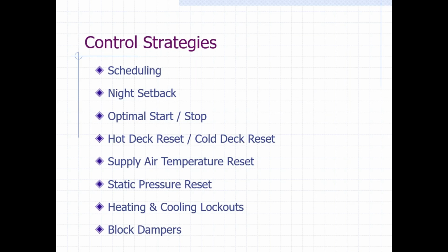climates. If you turn things off, then you might have some humidity issues in the building. And the last thing you want is mold. If you have an energy efficient building with mold, pretty soon you're not even going to have a building, and that's a bad investment. It's better to have no mold and waste energy. So maybe scheduling turning things off is something you might not be able to do in some areas of the country. You sure can in California. It's not going to be a problem out here.